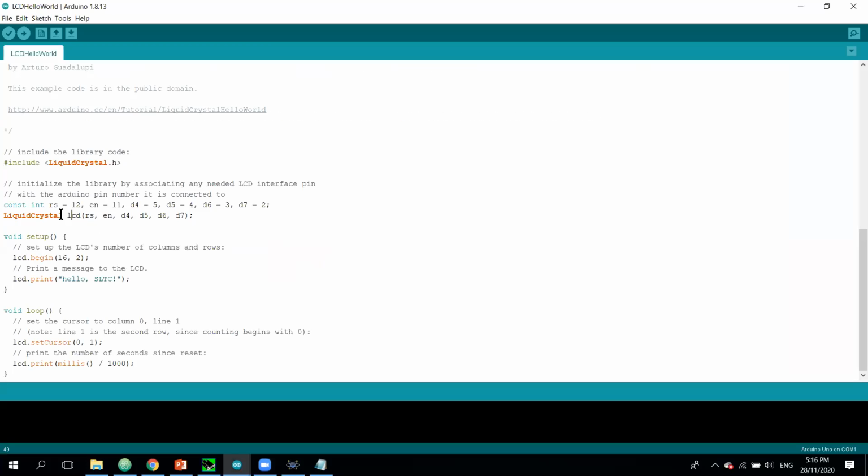Now you are going to define an LCD display here and name it. You can use any name. I'm going to use, like, test. Then you have to change this one to test, here, here, and here, because you have created the LCD display with the name test.